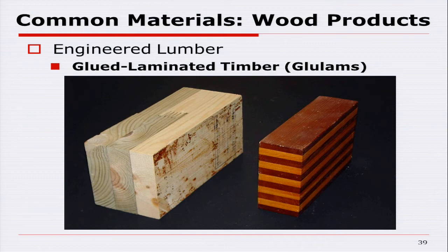I don't want to have a bin full of lumber where I have real weak ones and real strong ones, because when I grab it, I've got to assume that I've grabbed a weak one. And all my design properties are based on the weak one, and I'm wasting all the strong lumber. So you want to make sure that everything has about the same strength.